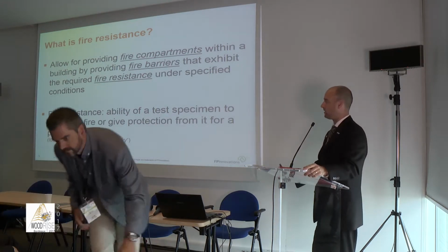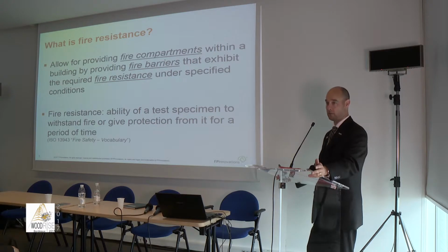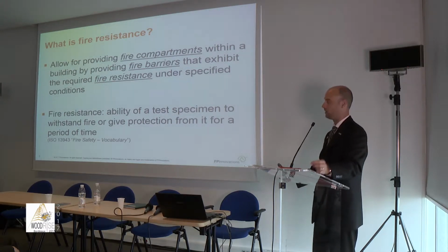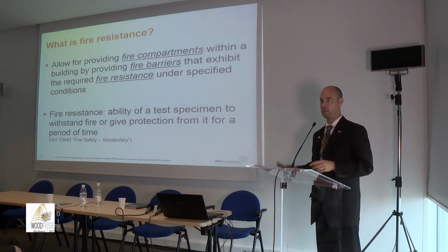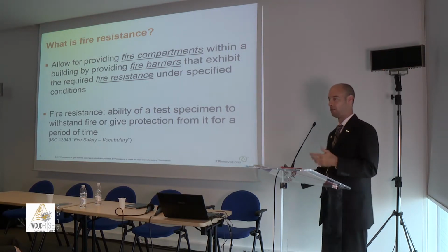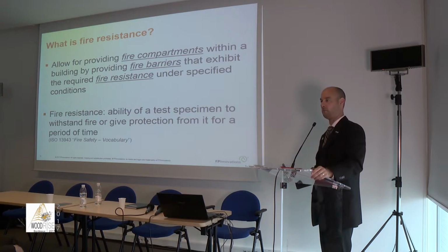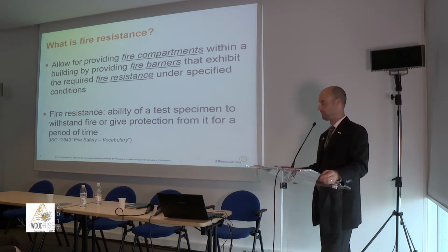So what is fire resistance? Essentially, it's a concept that allows for providing fire compartments within a building by providing fire barriers that exhibit the required fire resistance under specified conditions. So there are many defined terms that are all interrelated in that whole concept. Fire resistance is essentially just the ability of a material or an assembly to resist some criteria for a given period of time.